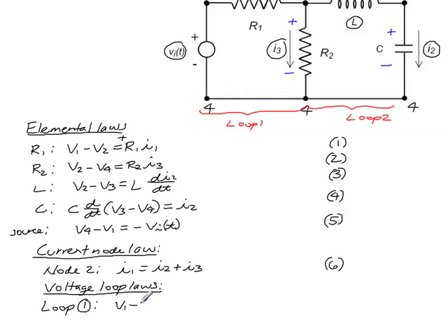We start there at node 1. That's the voltage across the resistor. And then we have V2 minus V4, that's across the second resistor R2. And V4 minus V1. We check to make sure that we have our signs right in all this, and we see our check works in the sense that this V1 will cancel with that, V2 cancels there, V4 like that. So for sure that works out in terms of signs.